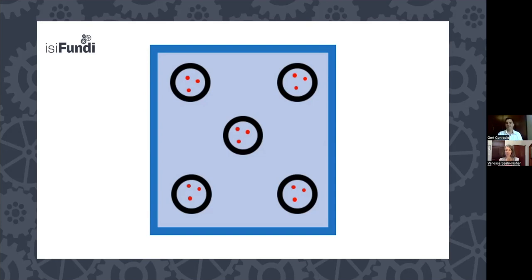So we don't actually hold a single reading as the make or break of a coating application. And I think that's quite important for us to realize. Because we're taking an average of averages, we've discounted the fact that you might have a particularly high peak that doesn't have a coating that's as thick as a deep valley. But because we're taking that average of averages, we now take the numbers that we've developed for our 10 square meters, and those are the numbers we decide, yes, this meets the specification, or no, this does not. Have I understood you correctly?